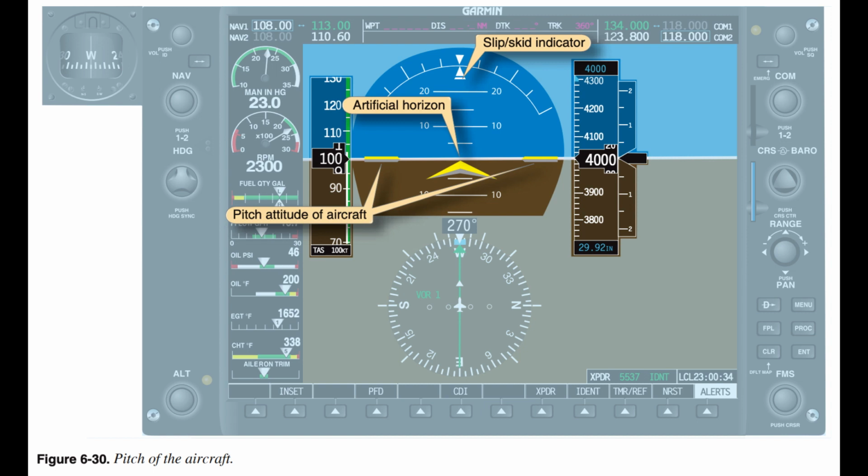In straight and level flight, the pilot maintains a constant altitude, airspeed and, for the most part, heading for extended periods of time. To achieve this, the three primary instruments that need to be referenced in order to maintain these three variables are the altitude, airspeed, and heading indicators. Primary pitch.